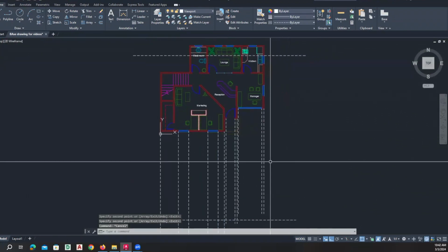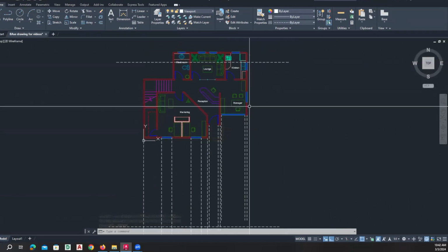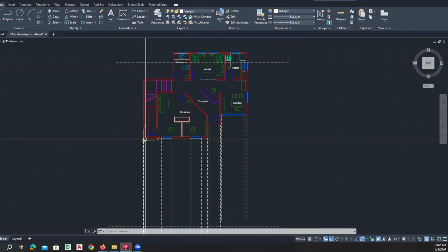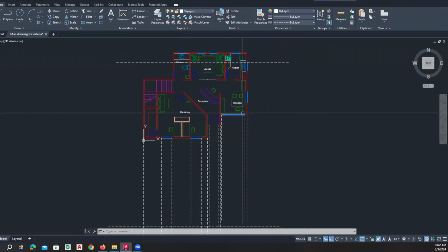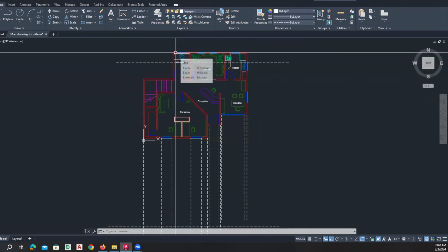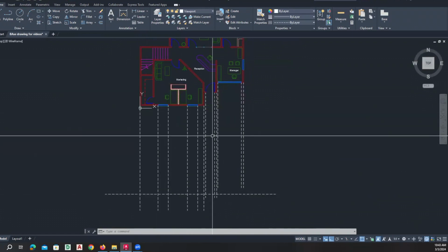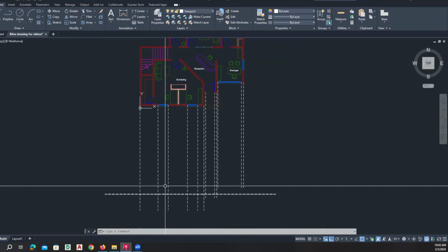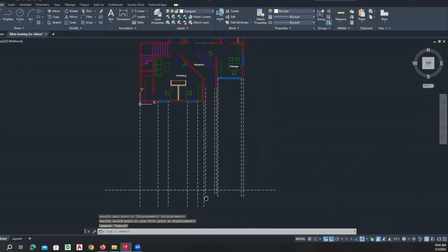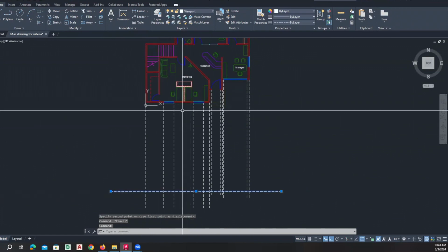And just like any other orthographic projection, like an elevation, we're not concerned with the sides, right? Because this is a true elevation. We're looking at this straight on, not in perspective, but straight on. So we see only the faces that are directly facing us and the ones that are perpendicular to us, and certainly the ones that are behind the building, we do not see. So these are all the corners and important aspects of the elevations in which we are projecting down to our ground plane. And some of these lines are a little bit short, so let me just stretch them a little bit like that.